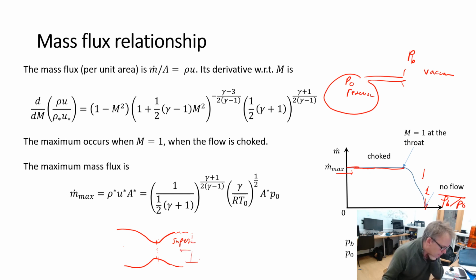That normal shock will regress back to where the throat is, it'll become weaker and weaker, and then once it meets there, the strength diminishes, it becomes sonic on the left and the right. And once it becomes sonic on the left or right, then the condition of being choked is lost.